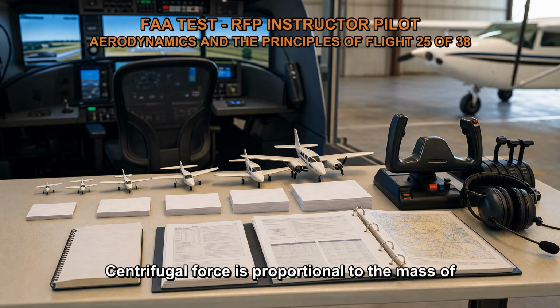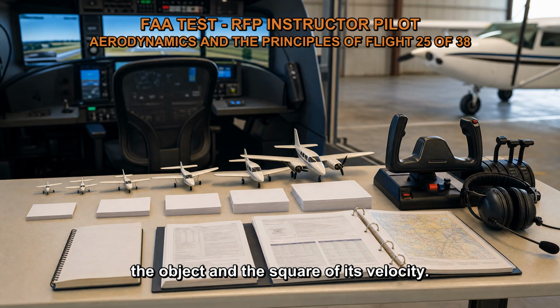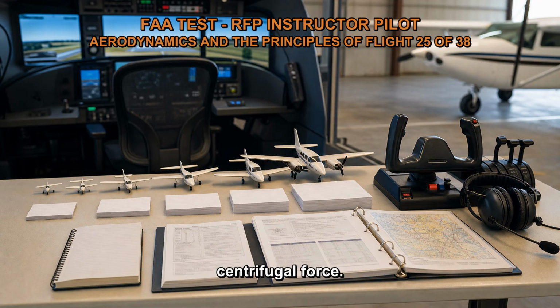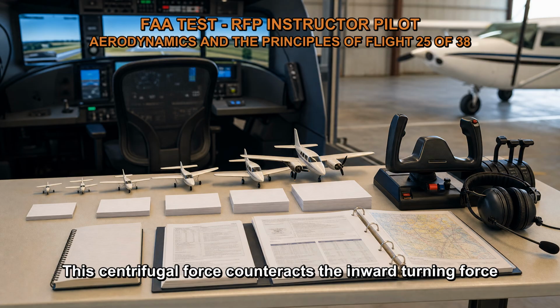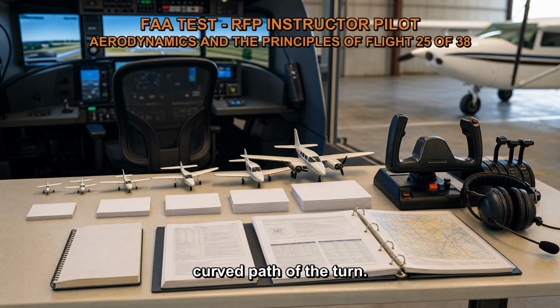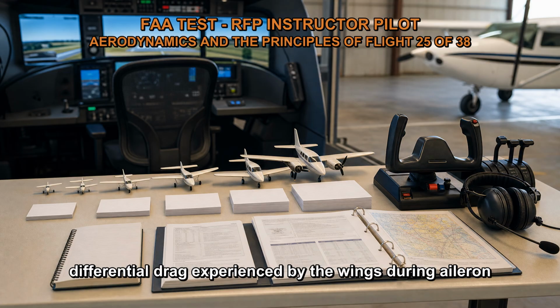Centrifugal force is proportional to the mass of the object and the square of its velocity. As the glider turns, the velocity of the aircraft increases, leading to an increase in the centrifugal force. This centrifugal force counteracts the inward turning force and helps maintain the glider's trajectory along the curved path of the turn. Adverse yaw is a phenomenon related to the differential drag experienced by the wings during aileron input.